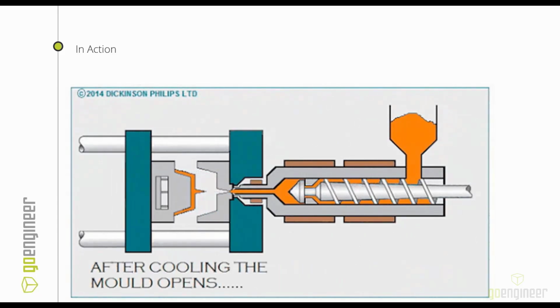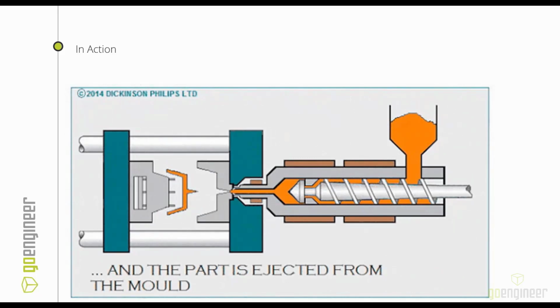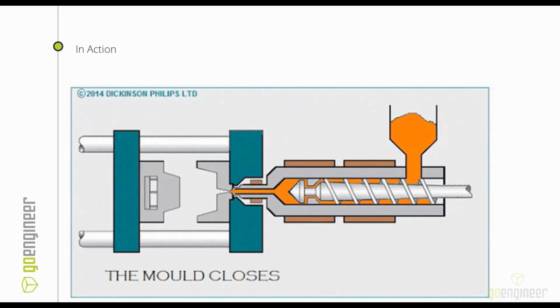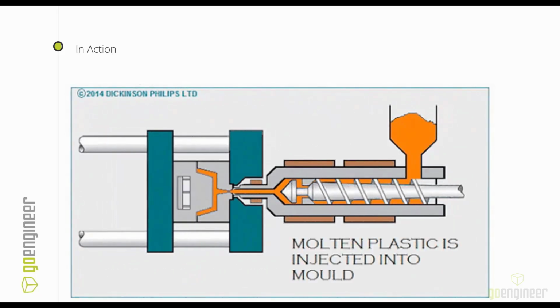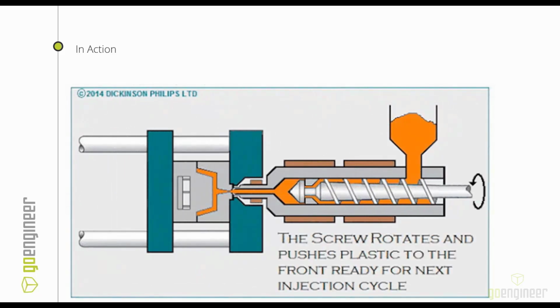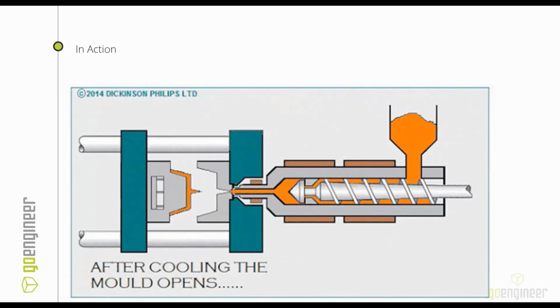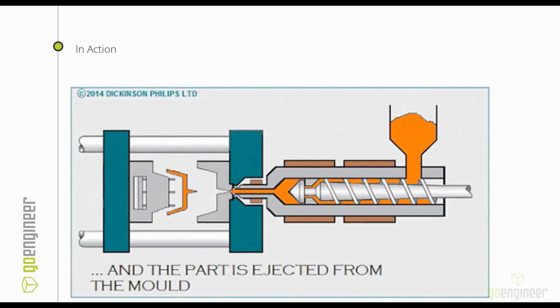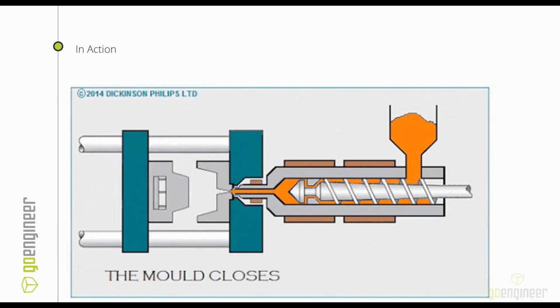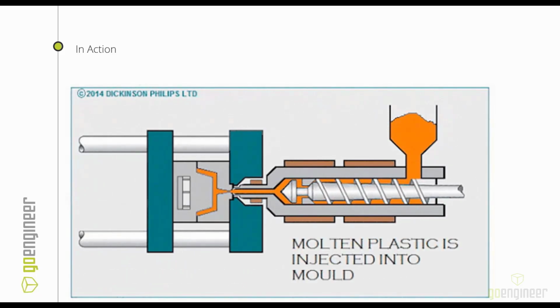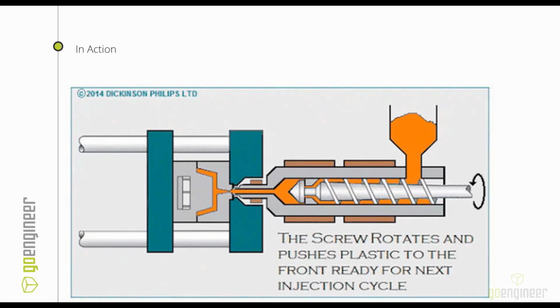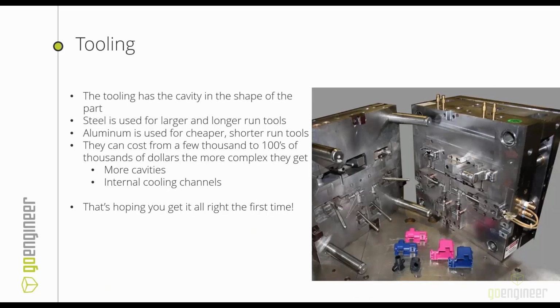These are more for when you need 100,000 parts or hundreds of thousands of parts out of a machine. Plastic, you could crank them out on an injection mold machine very quickly. And these prices for getting the tooling made have nothing to do with the price of the actual injection molding machine. So that'll all factor into runtime and materials and people actually owning and operating it, or if you have these machines in-house. So the tooling themselves can actually be very complicated, even for something fairly simple.